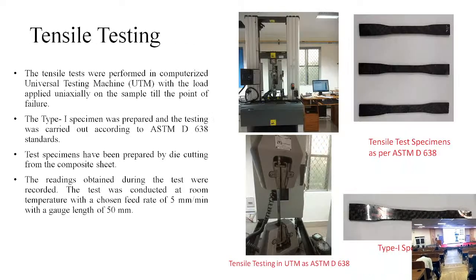The first test is the tensile testing of all the 3 composites, 3-ply, 4-ply and 5-ply, which I did with the UTM machine according to the ASTM D638 standard.